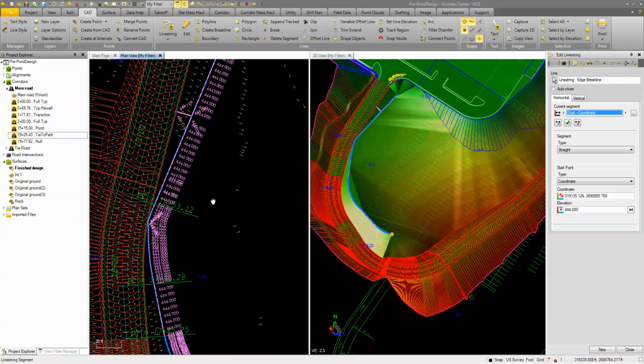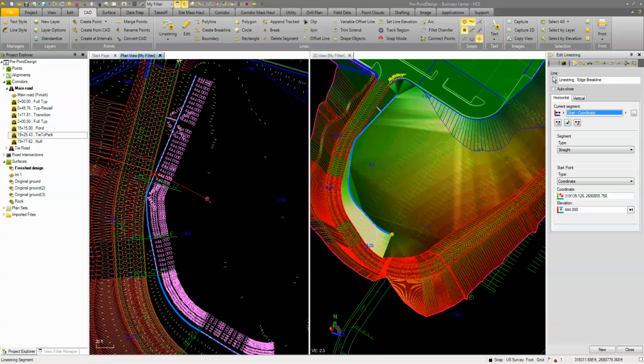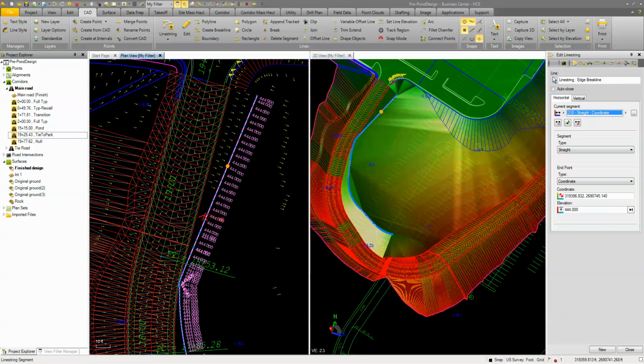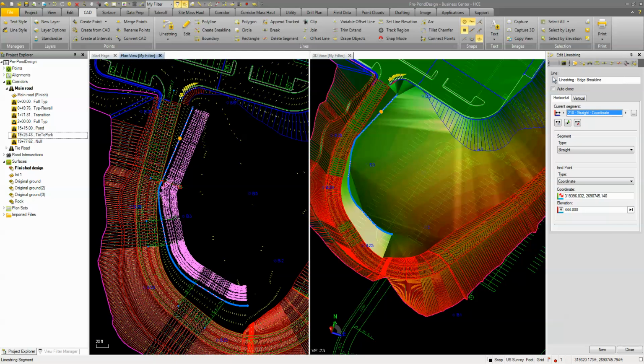the corridor to put all these vertices. Before I actually edit this, let's pick on here and get rid of this little segment. That's where our transition was, so I'm just deleting that so it comes back to here. Now I want to weed out some of these vertices. I don't need them all.